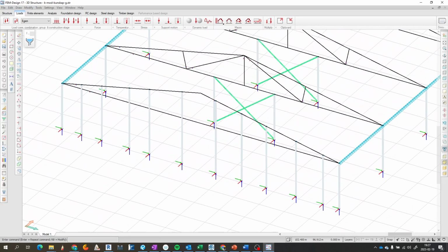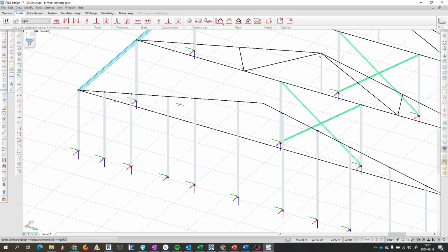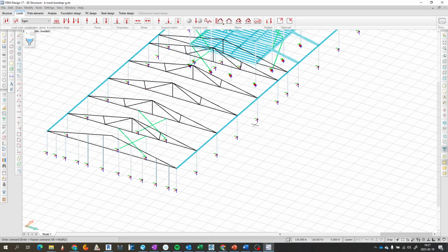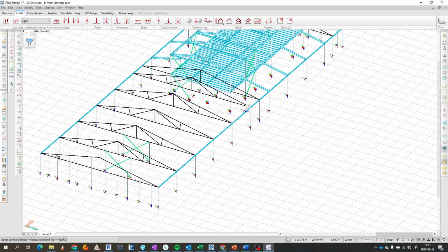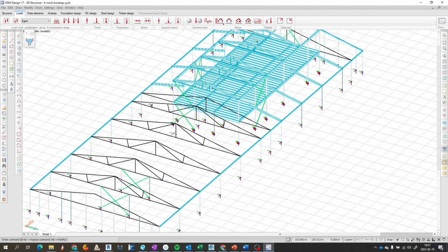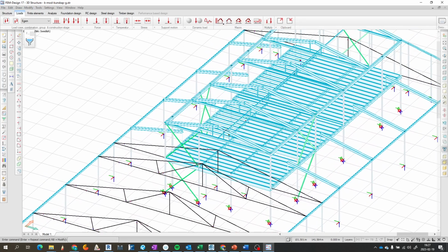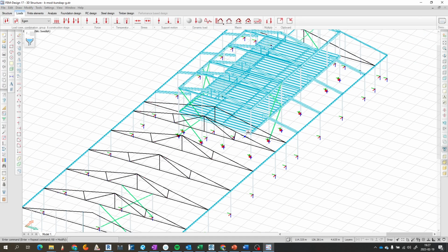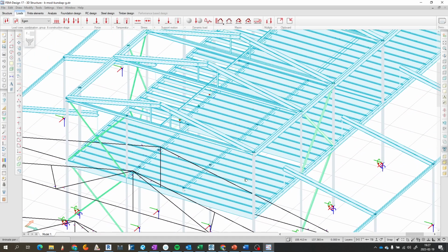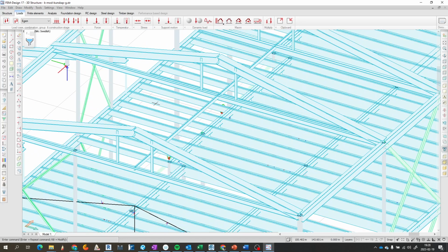In the south view, you see that the steel columns are going to reach the roof, and on the long side we have steel columns, the hallway. We have trusses, we have stabilization elements as well, and of course that was on the first floor, and the second floor, which is a slab here, but this is constructed with timber beams.